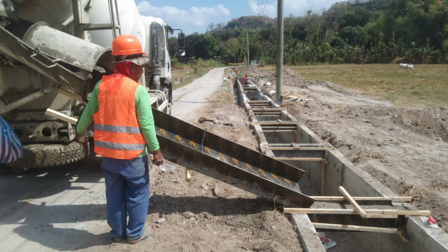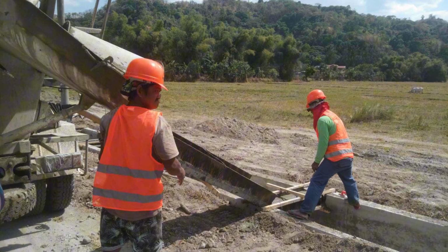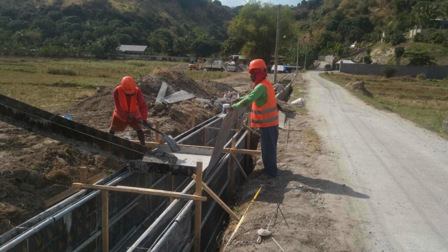Concreting. The concrete to be poured should be properly vibrated for the concrete, especially the aggregates, to fully spread into the base. Installation of wall reinforcement on the previous wall starter bars should be continued. A proper concrete cover should be considered when closing the formworks; at least 50 millimeters has to be considered to protect the rebar from possible corrosion due to sulfate attack.